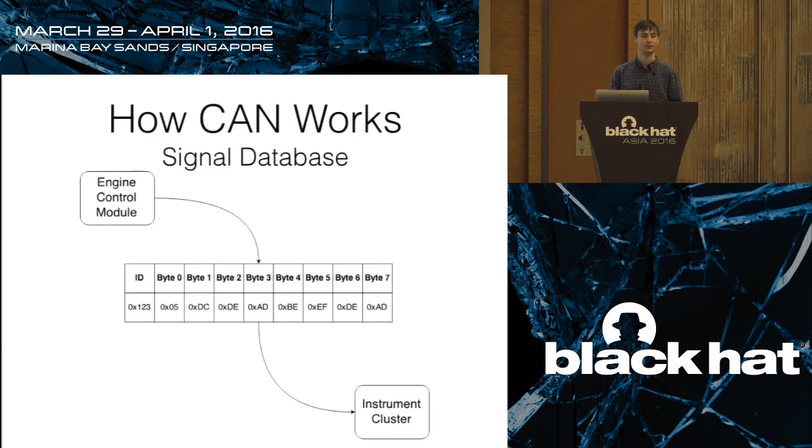Now, when you first connect to a CAN bus, you're going to see data flying around, a lot of these, all over the place. And what's actually happening in your vehicle is decoding. So, it's quite simple. The bytes of this message will have meaning, which is predefined at the time when the vehicle software was designed. So, in this case, these first 2 bytes might be an engine RPM. I actually saw a CAN bus just the other day where there was, in fact, a message, not that ID, but it was the first 2 bytes for an engine RPM, just direct correlation.